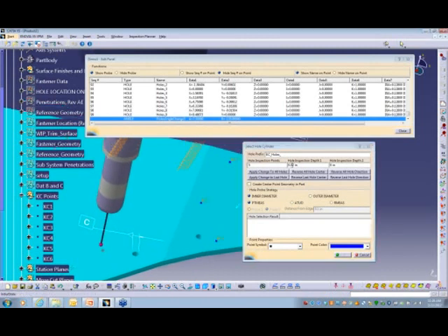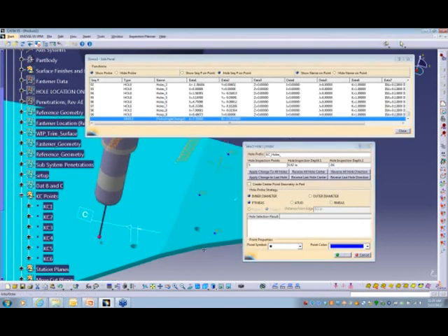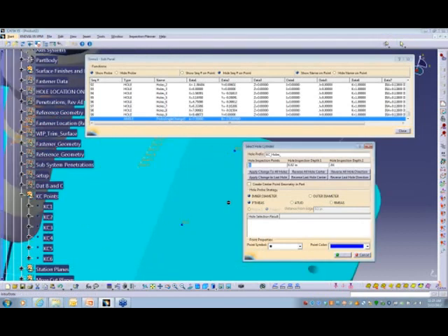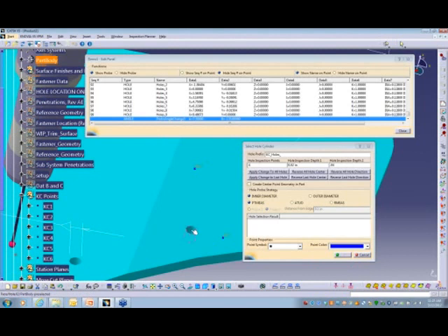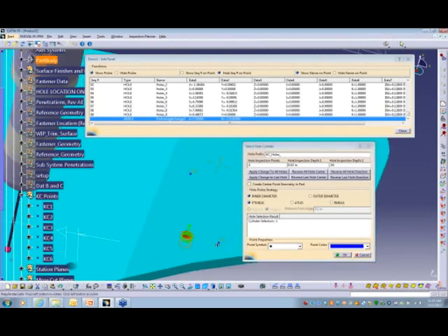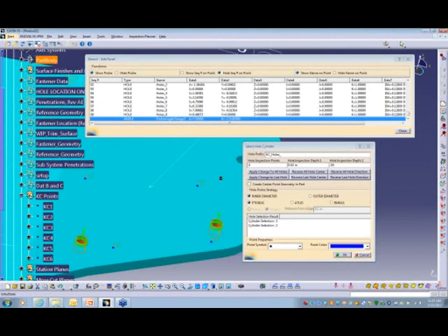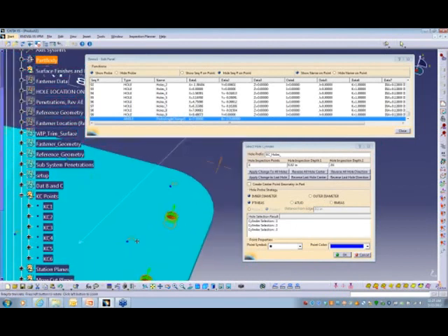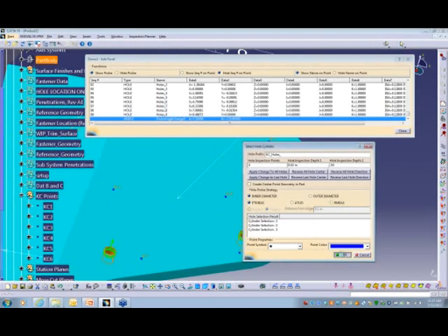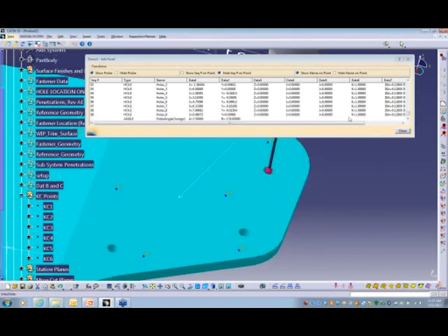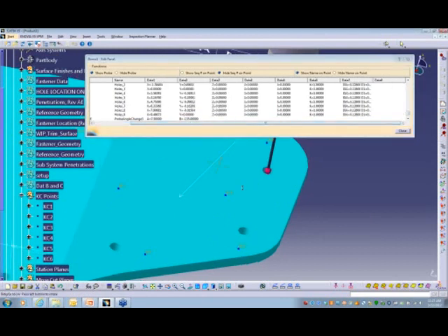We want to probe it, we could probe 2 depths if we want, so we can go down 20 and let's go down 40 because we want to make sure the vector's right. We can go back to 4. We pick the cylinder wall of the hole, reverse the vector. These 3 and say OK. So now we end up probing these holes in 2 spots.